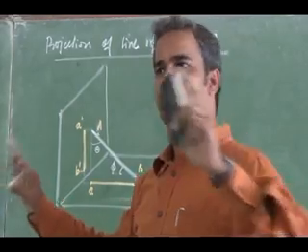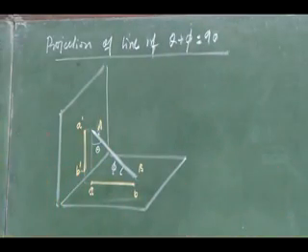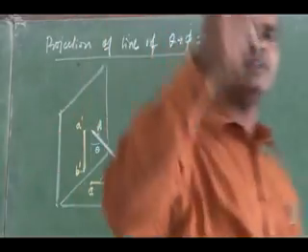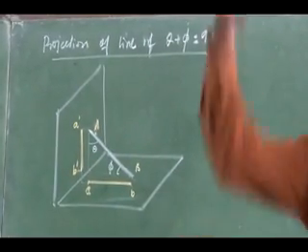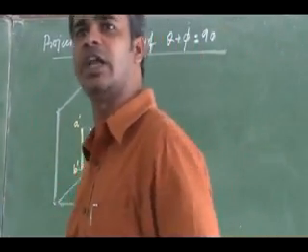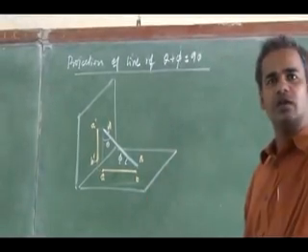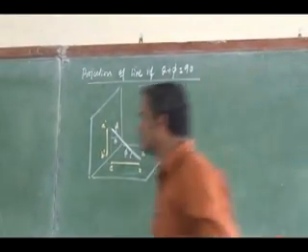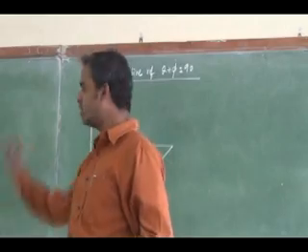So definitely, when you look at the problem, list out the data and add theta plus phi. For any case, you add theta plus phi. If it is 90 degrees, you can confirm that both the front view and top view will fall on a single projector line, not like this.